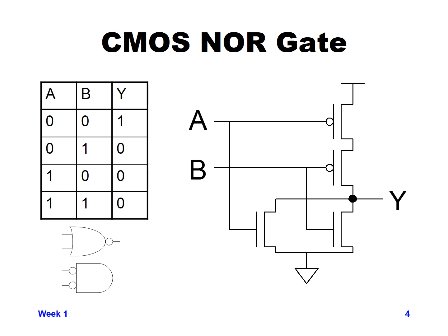So it's like a not A and not B type function, which is the same as an A or B not function. So that just shows the different symbols that produce the same function as a NOR.